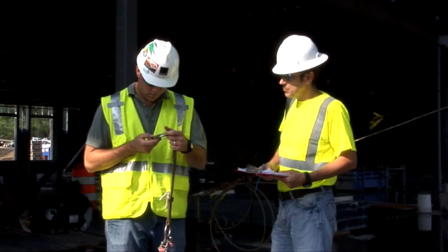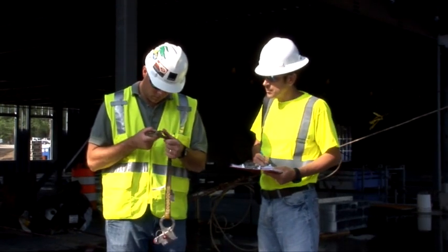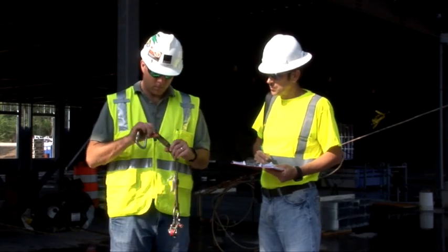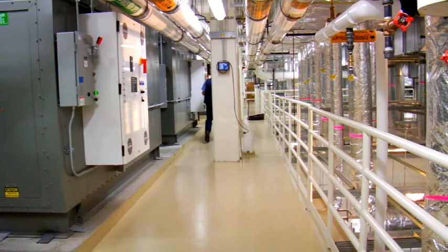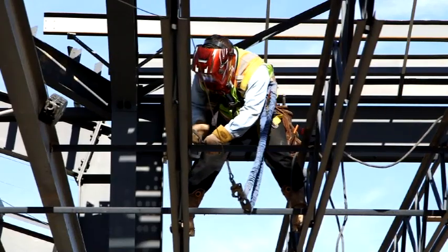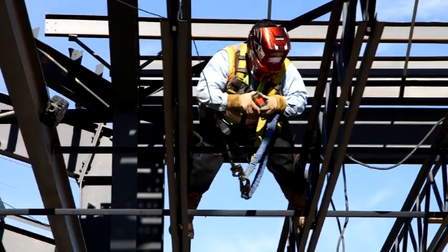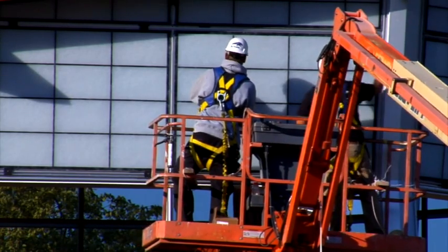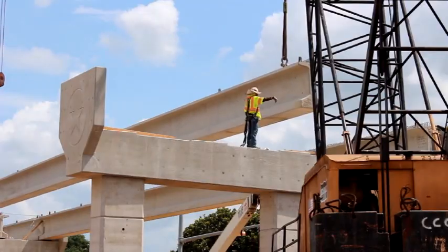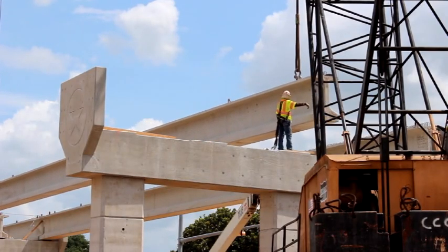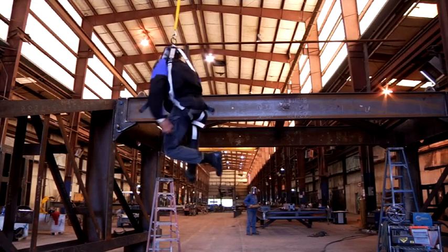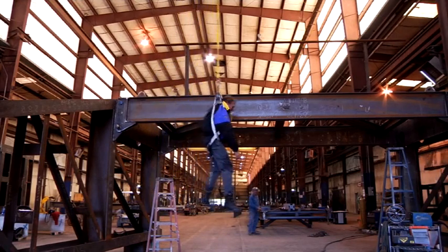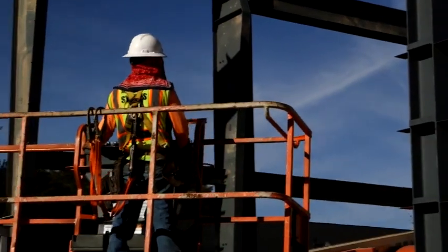Falls are a major safety issue, and using the right protection system is necessary to ensure your safety. Fall protection must be used when working on any surfaces more than 4 feet above a lower level in general industry and 6 feet in construction industry. Remember the ABCs of personal fall arrest systems: anchorage, body harness, and connectors, and how to use all components properly. Always know the total fall distance when using PFASs. Take training seriously, and finally, use all fall protection properly. It may save your life.